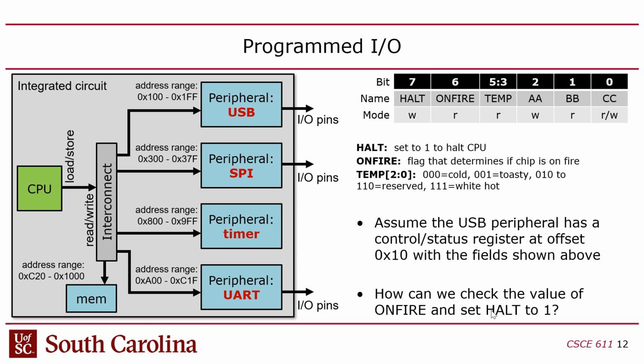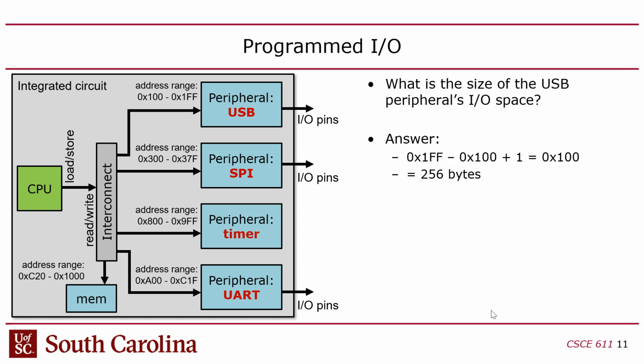Now in Linux, by the way, if you ever get into compiling Linux kernels, Linux has something called a device tree that keeps track of these addresses, and it's compiled alongside the kernel. The device tree is a special file that you write in text, but it gets compiled into a binary form, and the binary form is what's read when you boot Linux.